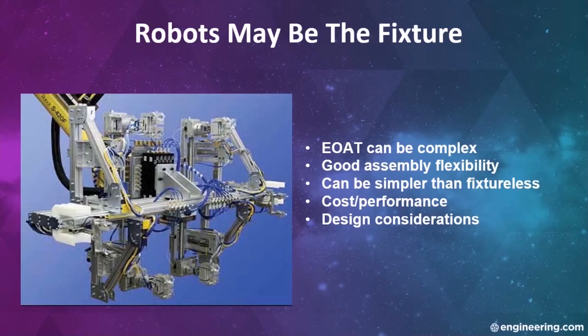For example, if your assembly needs a uniform flat surface across several parts, you've got a couple of options. One may be to design for precision assembly using piloted or doweled assemblies to hold everything in very, very close alignment. But it might be simpler and cheaper to coarse assemble first and then machine the assembly as a unit rather than design for precise assembly in the first place.